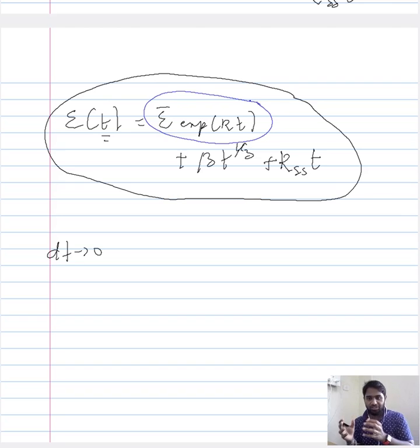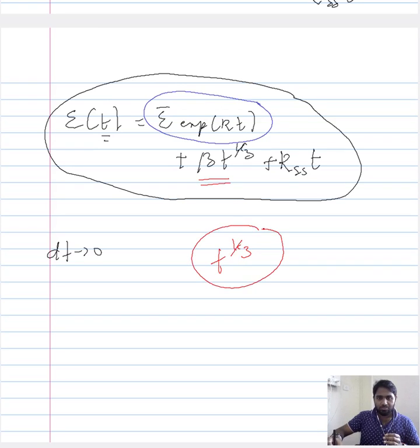And the subsequent stage, or the transient creep stage, he expressed in this form, where there is a factor that quantifies the amount of decrease in the strain and its relation to time is of this form, 1/3. So this is how the transient creep is characterized. And finally you have the steady state creep condition, which assumes that the creep rate is more or less constant.